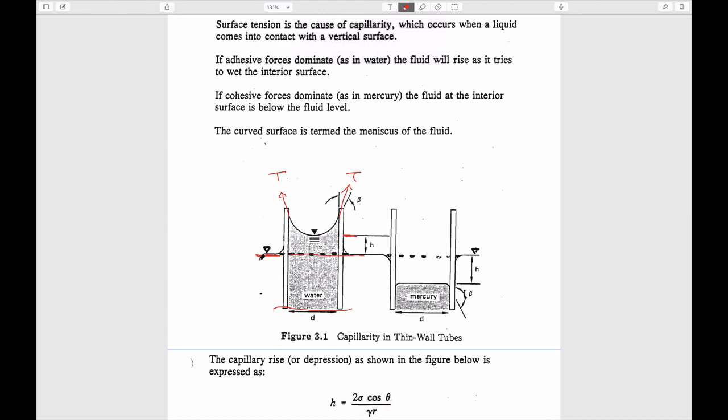The one conceptualization which you don't know yet, but which you'll learn on Monday, is that if you travel horizontally in a fluid, the pressure you get at this point here, which is atmospheric because it's sampling the atmosphere, if you go on a horizontal line and you can get there on a simply connected path, the pressure at this point is also atmospheric. And so you can cut off this tube here and imagine the water just dangling at this point here. And you can calculate what kind of force you have to apply to hold it up.